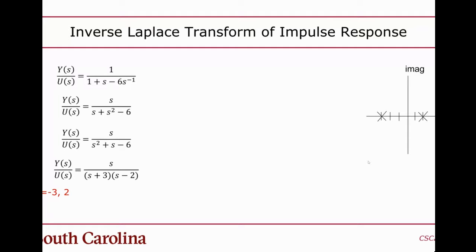Generally, you would show that using a pole-zero plot, which is just a regular Cartesian plot where the real value is on the horizontal axis and the imaginary value is on the vertical axis, which is pretty standard. The poles are marked as x's, and the zeros, which are the values of s that would give you a 0 value as opposed to an undefined value, are found by factoring the numerator and shown with circles. In this case we have a zero at s equals 0.